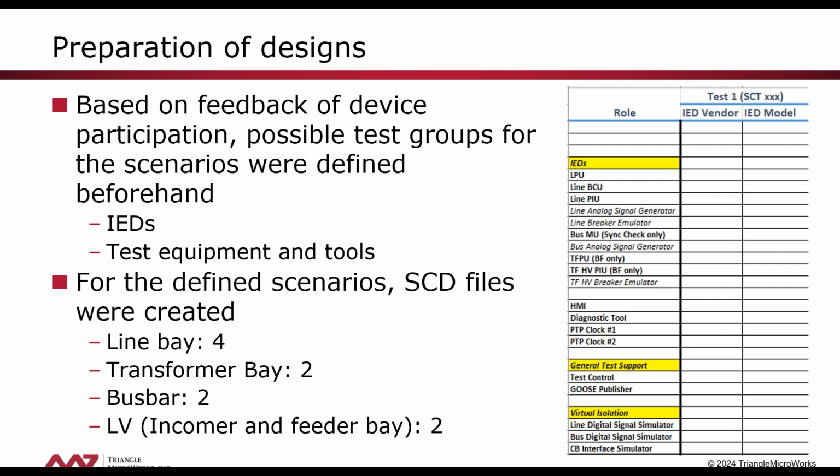Before the IOP, we also prepared the designs. Based on the feedback of device participation, once we knew which vendors will participate with what kind of devices, we created what we called test groups for the scenarios with all the IEDs. As an example here, that was a test group for the line tests.